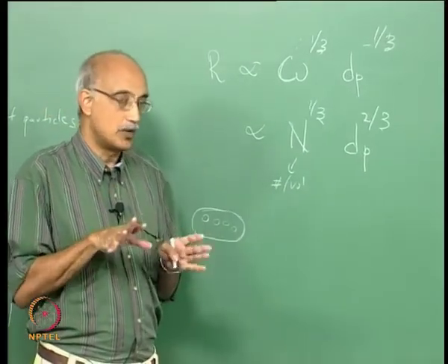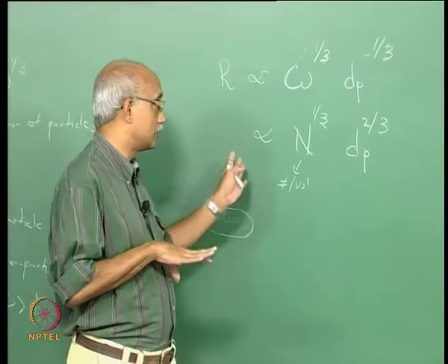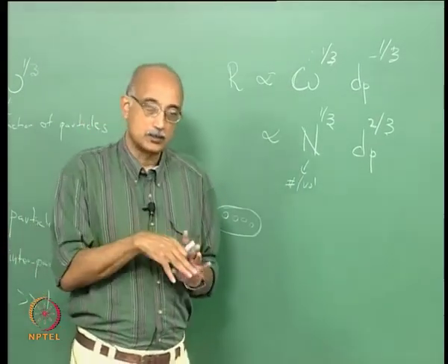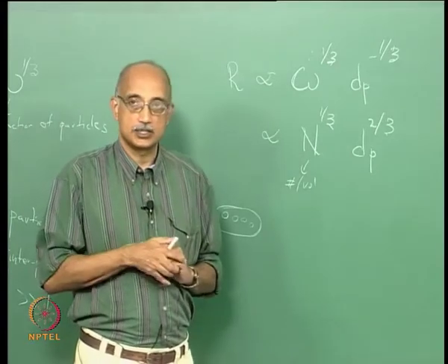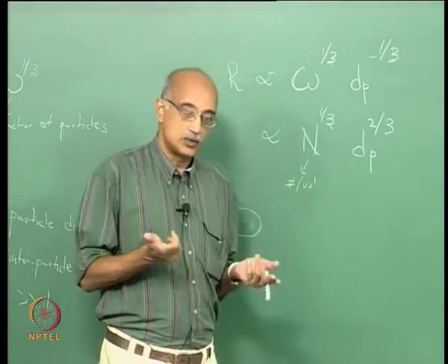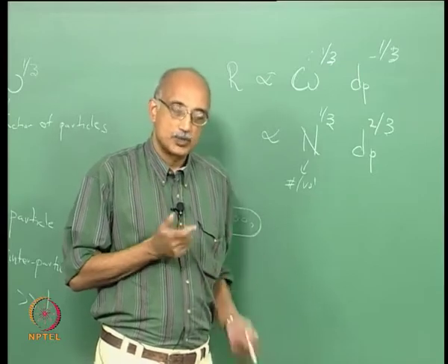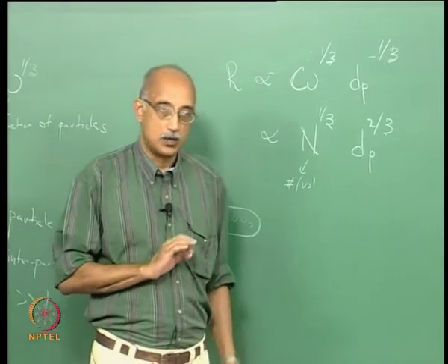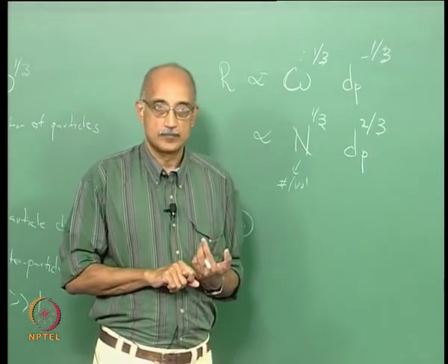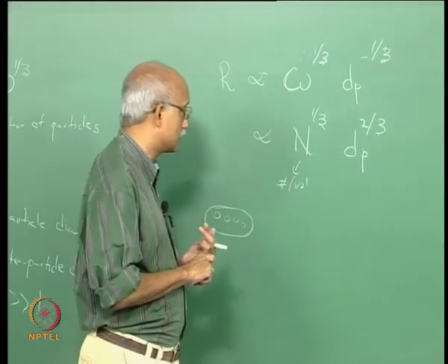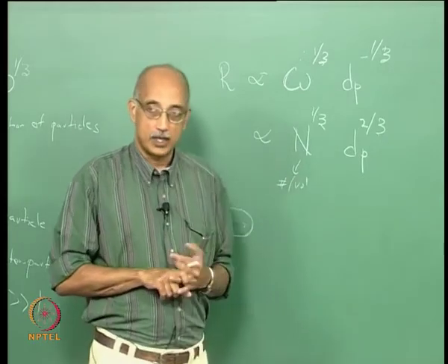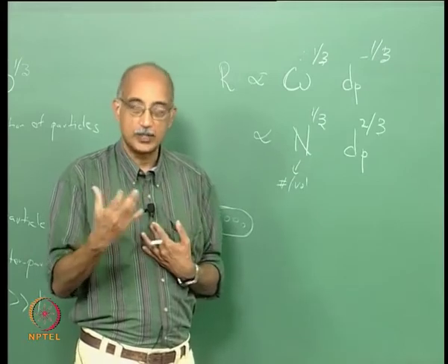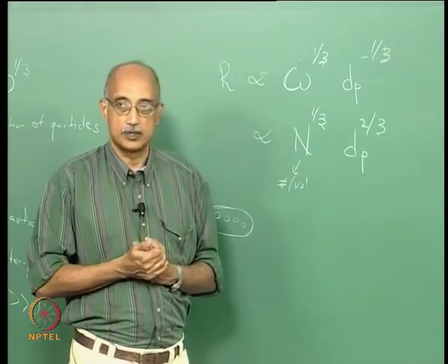But whichever way you formulate the equation, whether you look at it from a surface area viewpoint like Preston's law does, or you look at it in terms of the volume of indentation, the basic conclusion still remains that the most critical particle characteristics for surface polishing are particle concentration and particle size and the chemistry of the particle, whether there is any chemical interaction between the particle and the surface that is being polished.